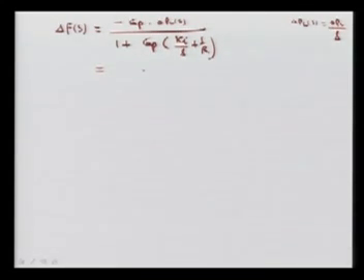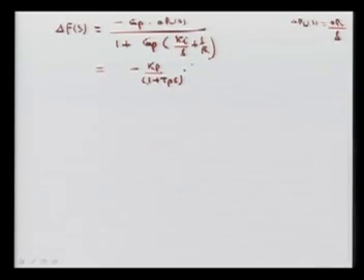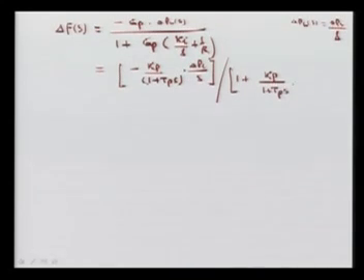So I can again simplify this. Gp is nothing but Kp times 1 over 1 plus TpS, and Tp we already saw is approximately 20 to 25 seconds. Here it is multiplied by some magnitude PL divided by S, and the complete division will be divided by 1 plus again Kp times 1 over 1 plus TpS, and we have here Ki, that is the gain of the integrator, S plus 1 over R.